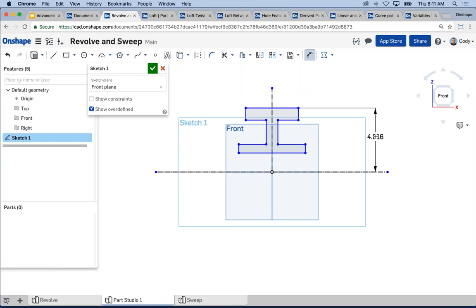So a tip that I have is when you're adding dimensions, this should be an actual diameter value, right? Again, we're creating a revolve profile. If you move your cursor past that construction line, it will automatically double the value and add that diameter symbol indicating this is a diameter dimension. So just a tip, and it's another big reason why having that construction line horizontally through the center of your revolve makes sense. It helps for dimensioning too, like in this example, right?